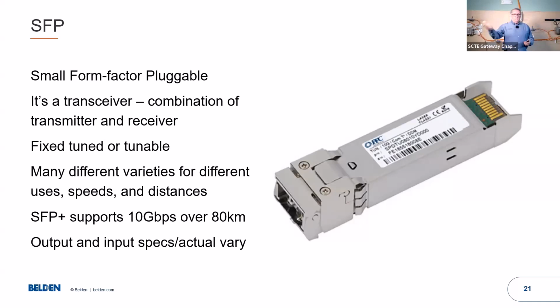So if you've got an SFP in the node that's not transmitting back to the head end and you need a channel 40, you put in a channel 38, it's not going to work. It won't pass through the muxes. So you have to be aware of what you are using. If an SFP goes bad, replace it with the same type. It's hard, if not impossible, to get something that's not designed to work inside of it. All right. So it goes for network and for head end. You've got to pay attention to what kind of optics you are using.